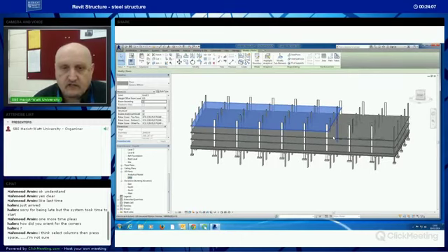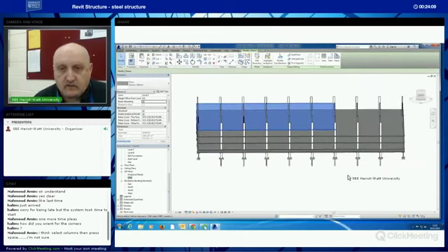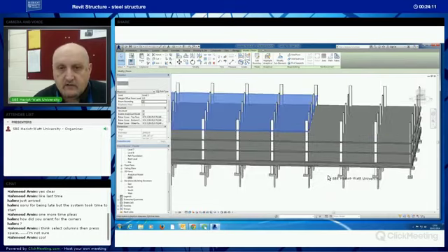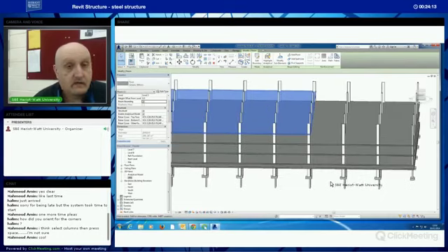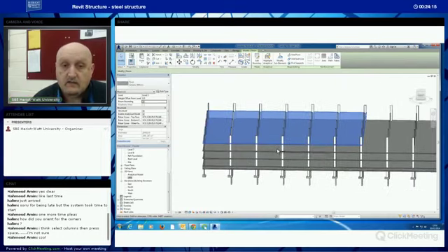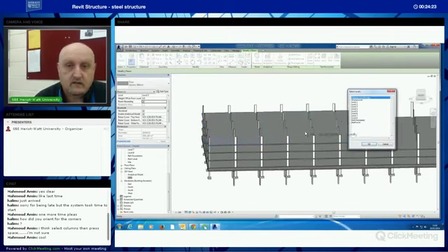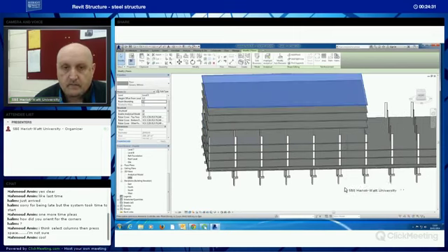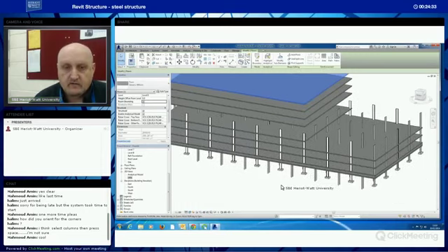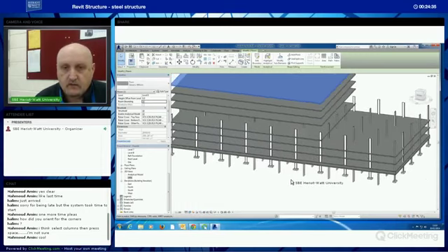Just have a visual check that your offset did in fact work, and I'm just going to check with them that they are there, they're fine. And then this floor, I'm going to take up all the way up through the rest of the building. So I'm going to copy it onto the clipboard and paste aligned. Now it's on level 4, I think, from memory, so I'm going to go to 5 and take it up to level 8. Alright, so that's the shape of our building.